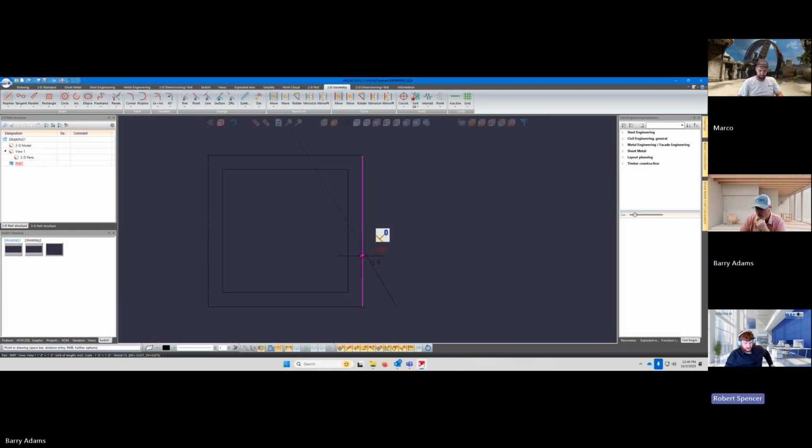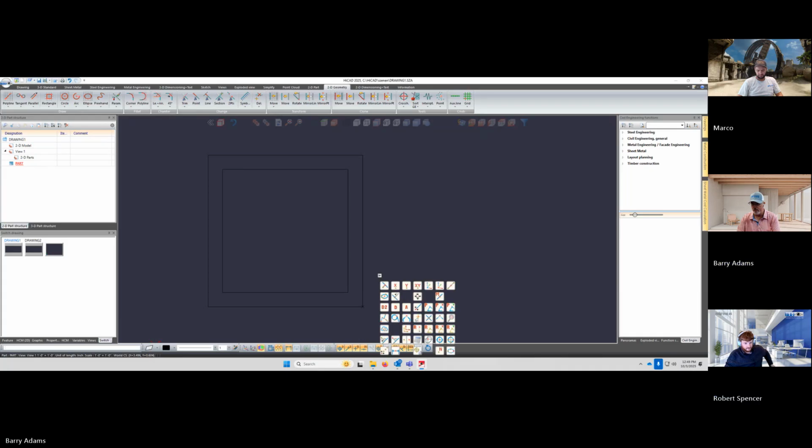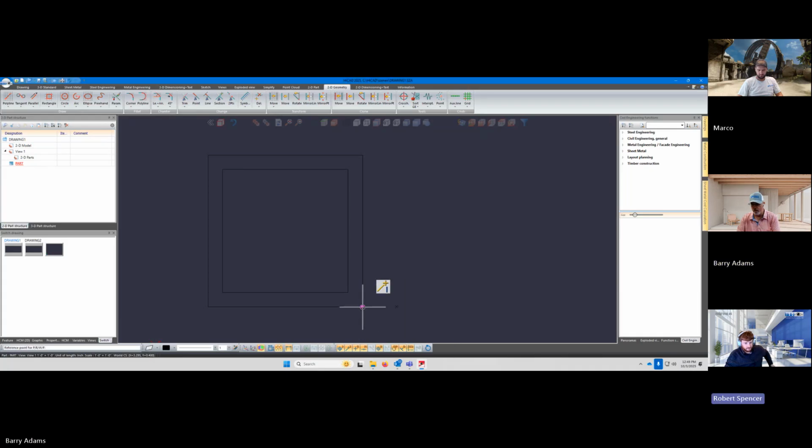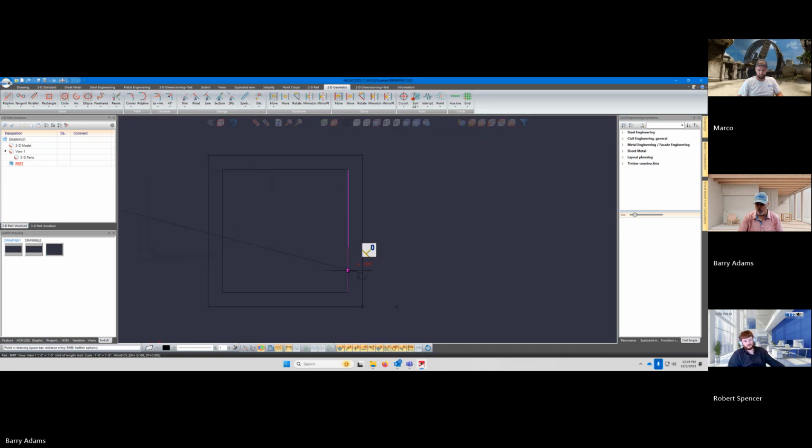Okay. We typed in the value for X instead of Y is what happened here. All right. So we're going to go with this. We're going to enter, enter and from point here, and say we want Y only. So say 0 space. That's what I forgot. 0 space, and then your value, 7/16. Okay. And then over. And then let's snap to the line you want to join it to. You don't have to go past it.